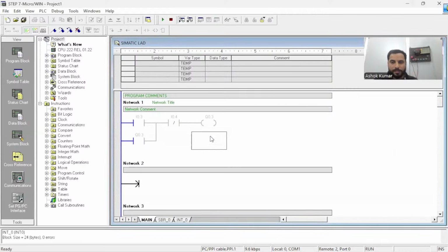If you put your PLC in stop mode, you cannot run this output now. See, now it's not working. Why? Because you have stopped running your program from the software. Now let's say you turn off the PC. In the case of Allen Bradley, this option was there when we made it remote program mode. If you make it remote program mode, the PLC program is not going to work, although it is already loaded.